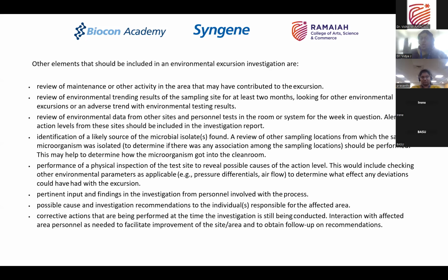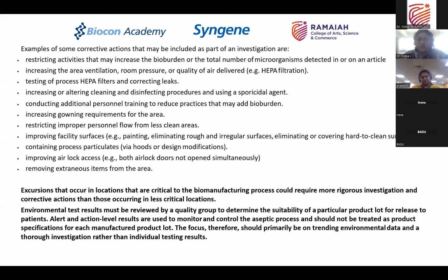And you have other parameters that you maintain in a sterile area. Your airflow and the pressure all have to be maintained, and you have to check whether the airflow is free of spores or microorganisms. These are agents that you have to keep checking every now and then.